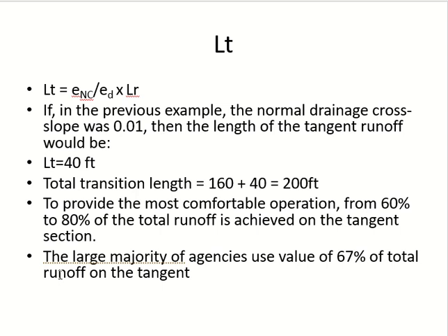So what we do to avoid the confusion for the driver, and to give him an indication that the curve is coming, is we do 60 to 80% of this before the curve, and the remaining 20 to 40% on the curve. Got it? A major part has happened before the curve, and some remaining part is happening on the curve. Clear?